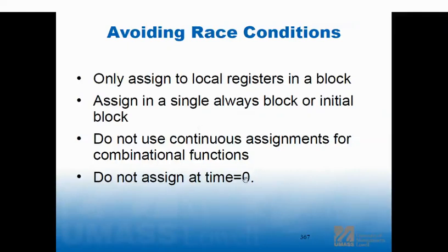And don't assign at time 0. Again, that's simulation stuff. You want to make sure that the RTL, right, that the DUT is reset with the reset condition. And that's not something we can talk about here. We talk about that in gate level sim.